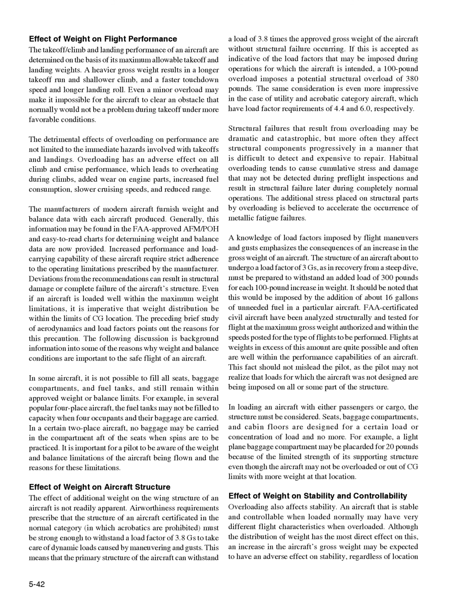Even if an aircraft is loaded well within the maximum weight limitations, it is imperative that weight distribution be within the limits of CG location. The preceding brief study of aerodynamics and load factors points out the reasons for this precaution. The following discussion is background information into some of the reasons why weight and balance conditions are important to the safe flight of an aircraft.